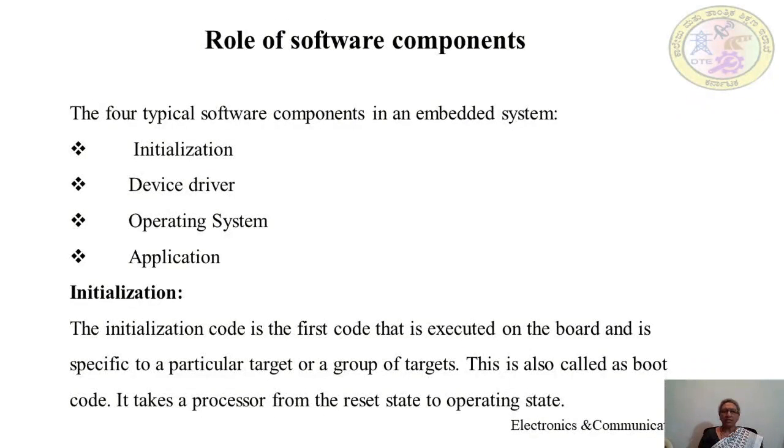The initialization layer or code is the first code which will be executed on a board, and this layer is specific to a target or group of targets. Whatever particular device you use, its features and characteristics must be known to this code, and accordingly it will initialize that target hardware.